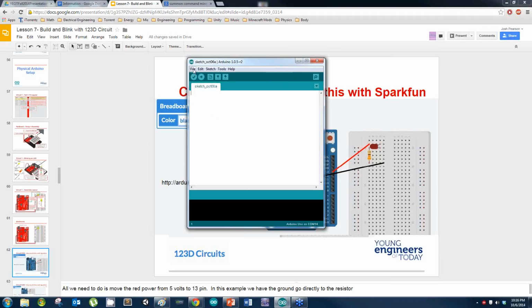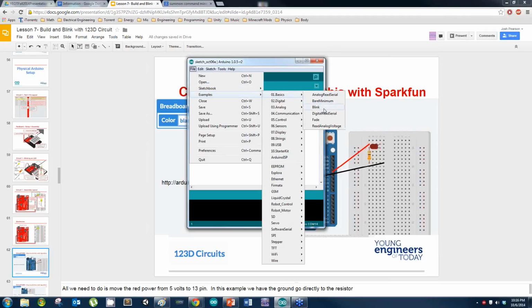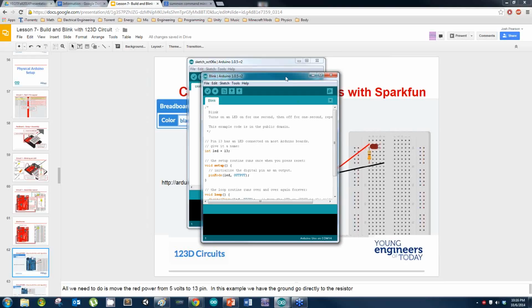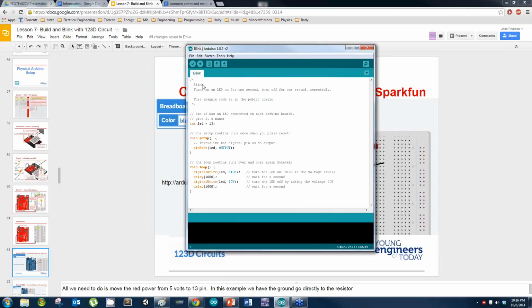Yep. And then go to File, Examples, Basic, and Blink right here. And you should see something like this. And go ahead and upload it. And then let me know what happens. Raise your hands when you have a blinking light.